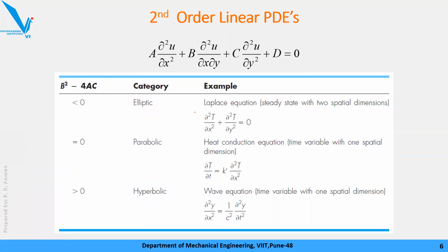next thing I'll explain about the example. If you look at the two-dimensional heat conduction, फॉर एग्जाम्पल आप प्लेट का एनालिसिस कर रहे हो. ठीक है, एक प्लेट है, आपने हीट सप्लाई किया है उसको, और आप टेम्परेचर ग्रेडियंट और हीट फ्लक्स पाना चाहते हो. Remember, it's a 2D problem, x and y, and it's assumed that plate है तो negligible thickness.